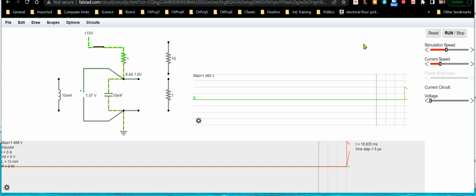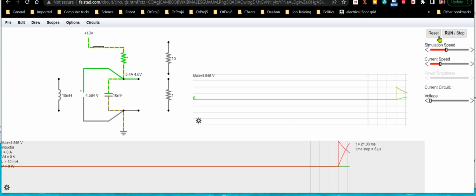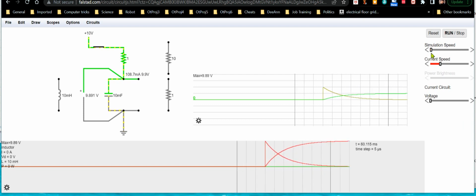Okay, but let me go ahead and close the switch. Alright, and you can see what's happening. At the very first, we've got a very high current, it's really 10 amps. I'll speed it up here so you can move it along. You can see the current flowing through it. It's like 10 amps, because that's what happens with a capacitor. The moment you hook a source across it, its current will be the max, and it'll never be as high as that again throughout its charging cycle.